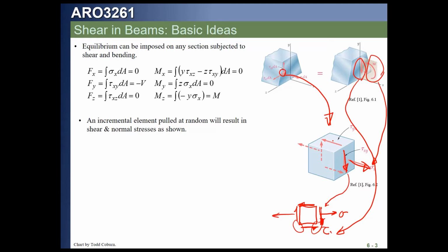Before, when we covered shear stresses, we looked at direct shear, where our distance dx was so small that we were pretending the force just reacted here. We said that would actually cause a moment and the stress distribution is more complicated, but when we use P over A for this kind of stress, what we're really saying is that it's just the average. Now we're going to look at how the stresses change from top to bottom of this section, using a more rigorous approach.